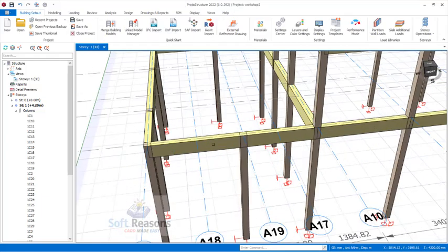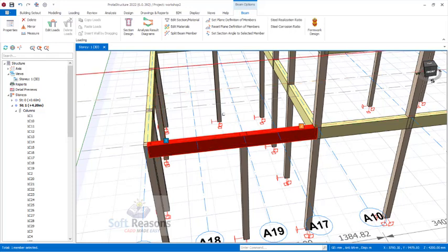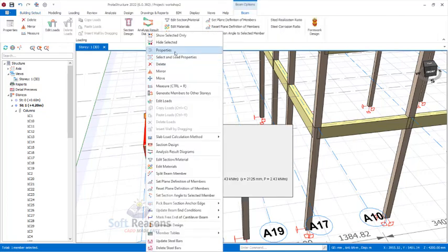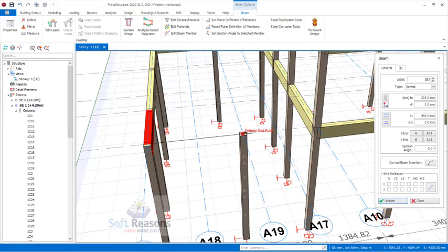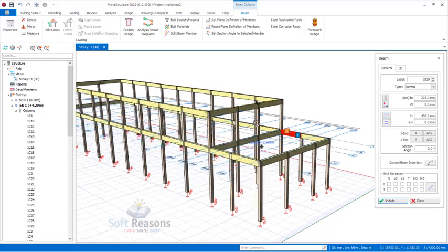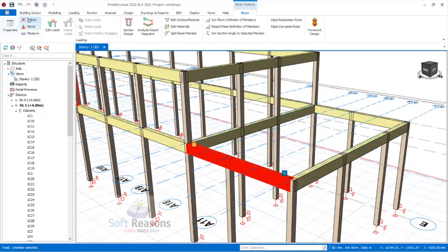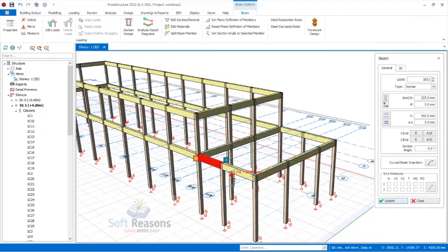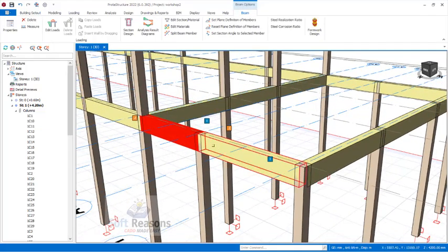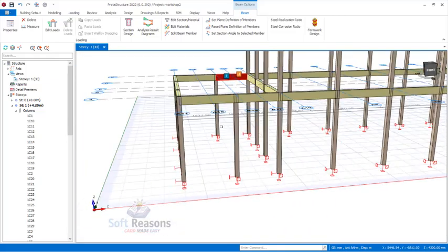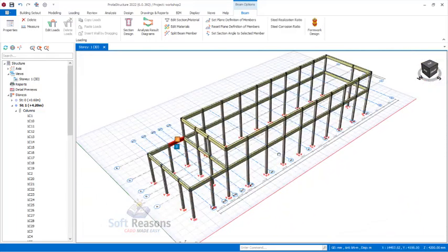Now this beam is not going to be valid again, since I have placed the column. You have to redraw this beam, so delete this beam, and then you can use the property of these other beams. Pick this point and then all the way to this point. After which you right click to get rid of the command, and then over to this side, select this and click on delete. Use the property by selecting the beam, right click and hit property to place it again. It is going to be a continuous beam. It is not supposed to be a single or simply supported beam, because there is a reinforced concrete support column at the center. So this is how it is supposed to be.